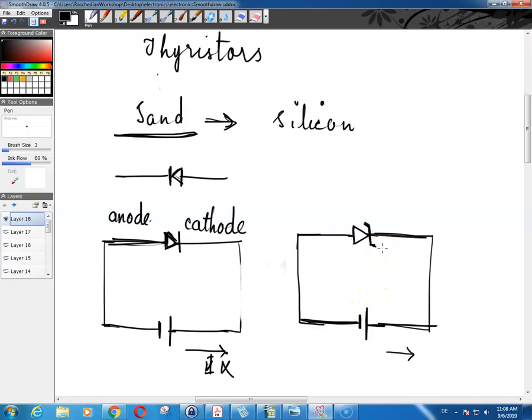But then once you reach that voltage threshold, the current starts flowing through your circuit. Zener diodes have voltage ratings, and of course power ratings as well, but the power rating is not that important. That is just indicative of how much current can go through your Zener diode. The power rating is also there in the case of normal diodes. But mainly these Zener diodes have some voltage rating, for example 5.1 volts. So the Zener diode is rated as 5.1 volts.